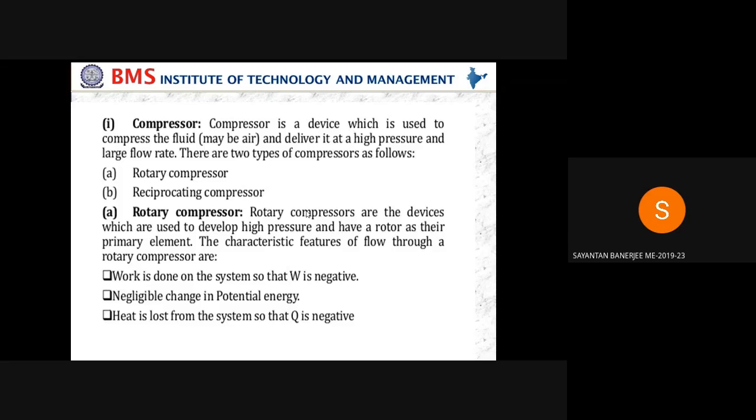Suppose at everyday life scale, we can approximately apply? No, sir. Bernoulli equation states that P by rho g plus V square by 2g plus z equals a constant for incompressible, irrotational, steady flow actually. So mainly we derived this for incompressible flow only, for water only. What actually your question was, I did not get properly. Can you ask once again?